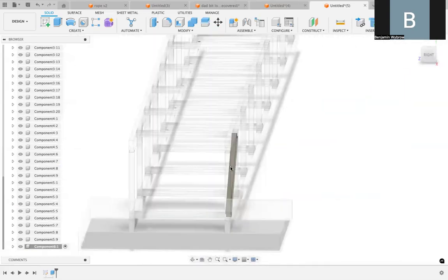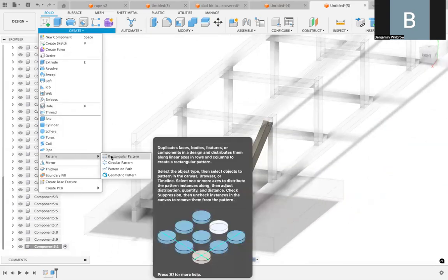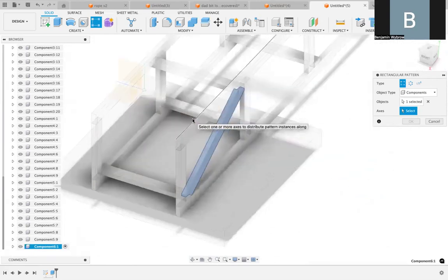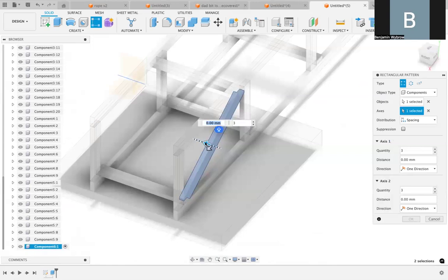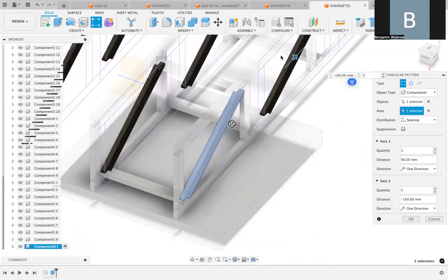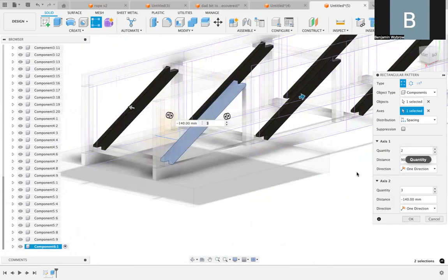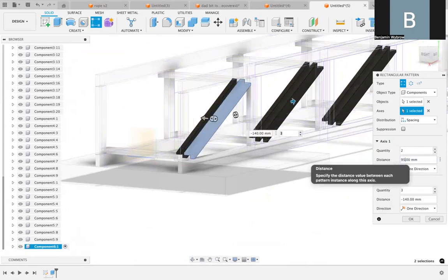And we are going to move them all around. So how do we do that? The rectangular pattern tool, boom, like that. We're going to click this piece. We're going to go axis, maybe click there would be nice. Yeah, that looks good. We're going to have 2 go that way, and we're going to have some go that way. And we're going to need this quantity to be 2 first. This spacing to be 95, I believe, from memory. Yep.